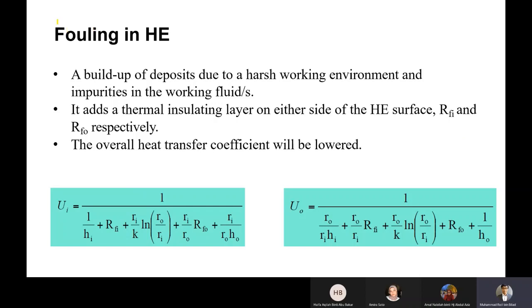There is a thing called fouling. This is the analogy of us; this is the cancer of heat exchangers. Normally when we design a heat exchanger, we say that it is fully clean, clean all the time. But over time, when we use the actual heating liquid and cooling liquid, there will be a build-up of deposit. This deposit will stick on the surface of the heat exchanger.